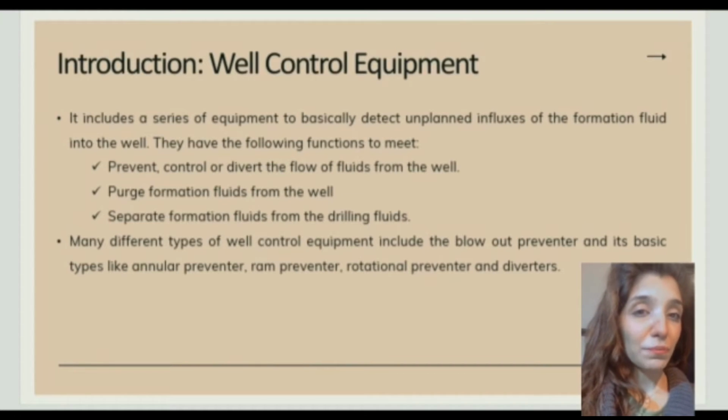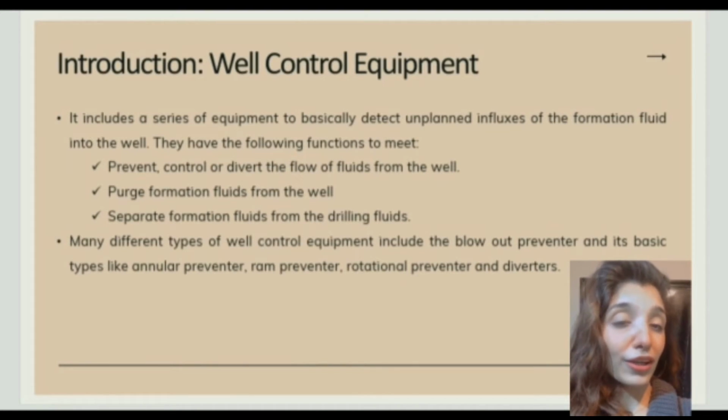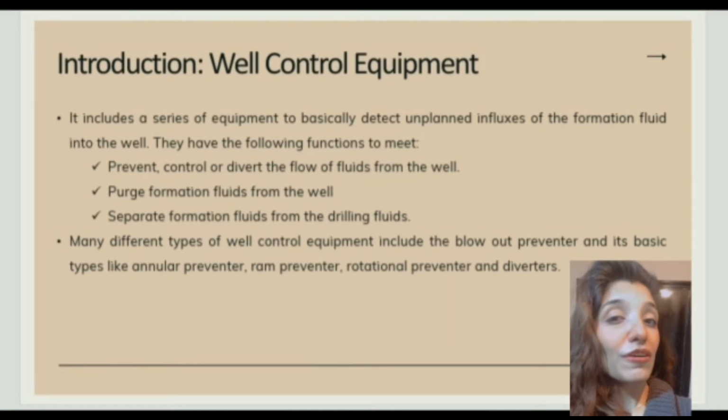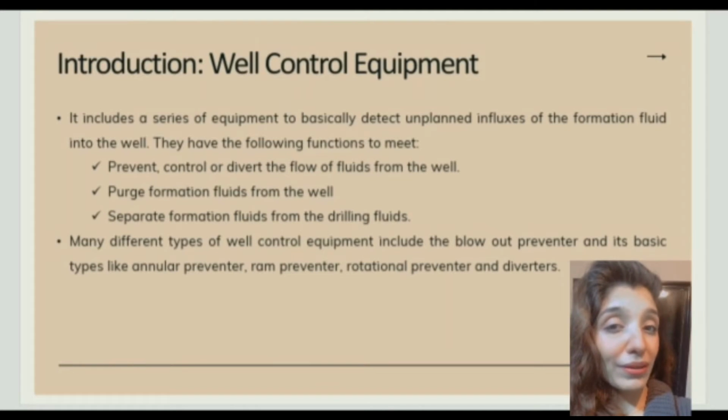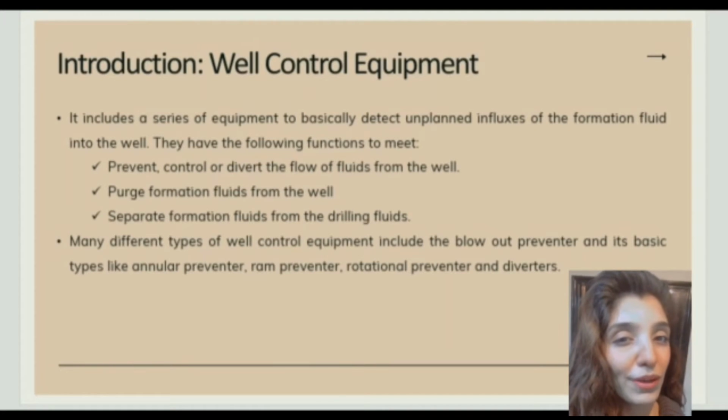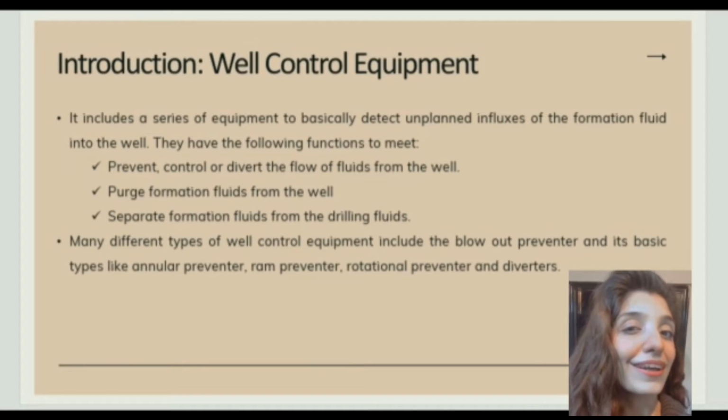It is a series of equipment that detects unplanned influxes of formation fluid into the well. The functions include to prevent, divert, and control the flow of fluids from the well, also to purge formation fluid from the well, and to separate formation fluid from the drilling fluids. There are many types of well control equipment, for example, blowout preventer, ram preventer, annular preventer, rotating preventer, and diverters.